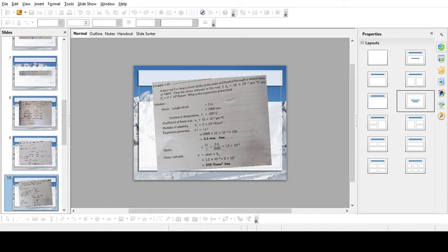Now by using these equations, sigma 1 A1 equals sigma 2 A2, and sigma 1 by E1 plus sigma 2 by E2 is equal to T into alpha 2 minus alpha 1. So the stresses induced in the bodies can be calculated. So next, let us go for a few problems in this.